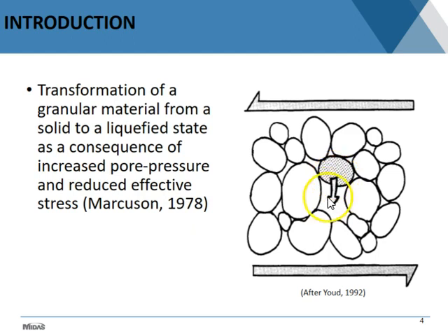So what happens is, as the particles try to reaccommodate, the pressure in the water goes up. And if it goes up enough, you can have a reduction in effective stress that can actually take the number close to 0 or to 0 eventually, so you can have a separation, so you lose contact between the particles and the particles start to float in a liquid phase. Okay, so of course the reduction in strength and stiffness is a clear consequence of liquefaction occurrence.